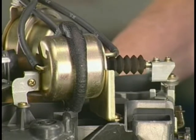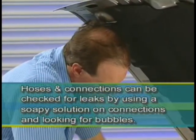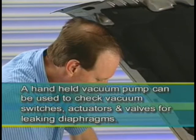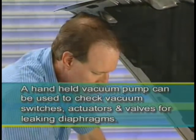Hoses and connections can be checked for leaks by using a soapy solution on connections and looking for bubbles. A handheld vacuum pump can be used to check vacuum switches, actuators, and valves for leaking diaphragms.